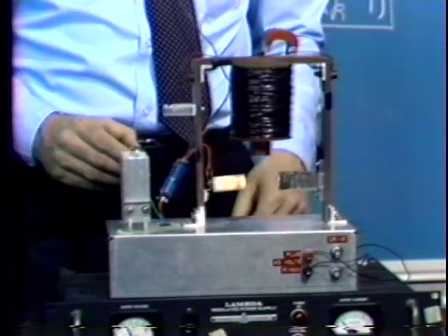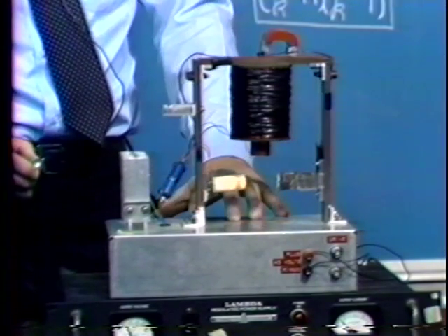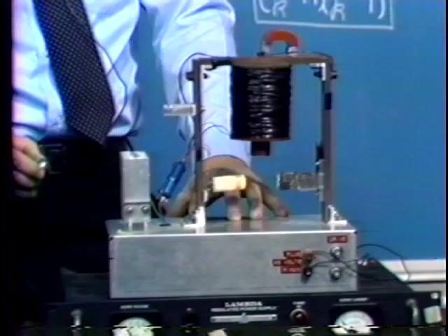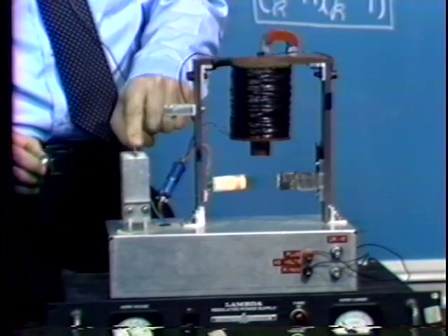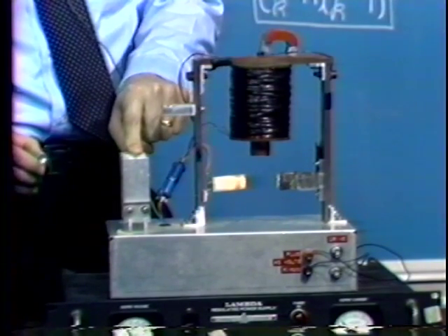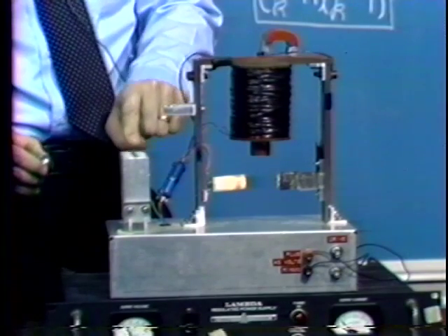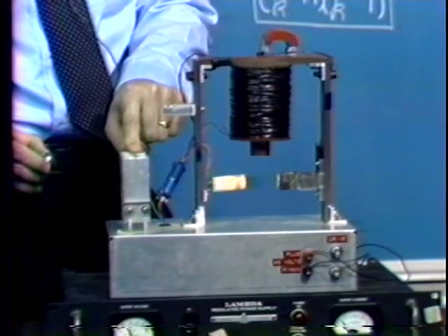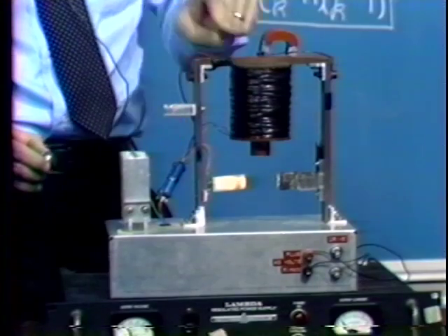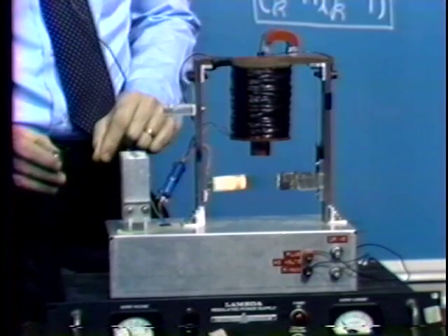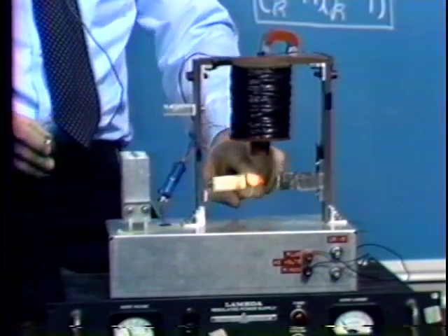And there's some electronics inside the chassis which drives a power amplifier, a power transistor on this heat sink. The output from the power transistor, the collector current of the power transistor, actually drives the electromagnet. And the strategy, of course, is to measure ball position.